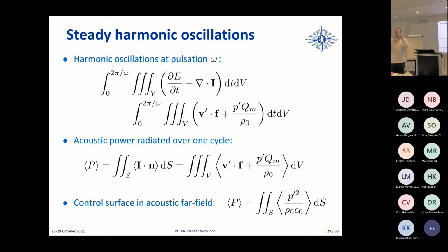Okay? And then the thing resonates as long as the grid is hotter than the surrounding air, and then eventually it decays. This one doesn't decay because there is a big fat electrical supply with it that we will hear in 1 second. So you have a source mechanism that is a modulated heat transfer. Now, modulated transfer, what kind of source is that? Monopole, dipole, quadrupole? Monopole, because there's entropy fluctuation, right? We have seen this. You have a strong entropy fluctuation due to the amount of heat that is extracted in an unsteady fashion around the grid. So we have to look at the monopole.